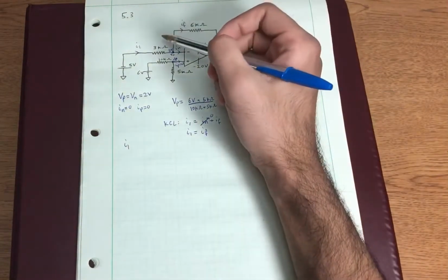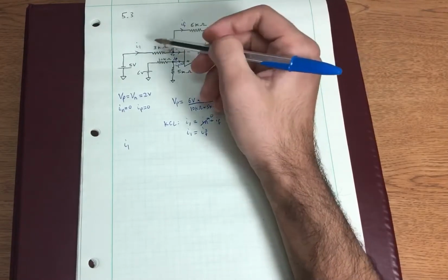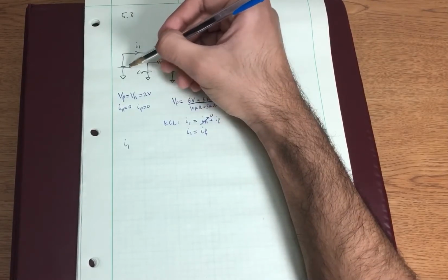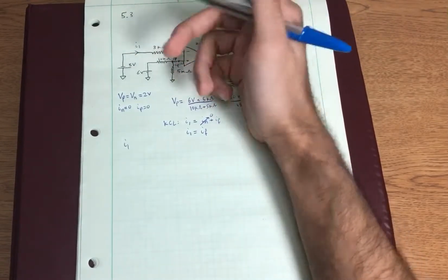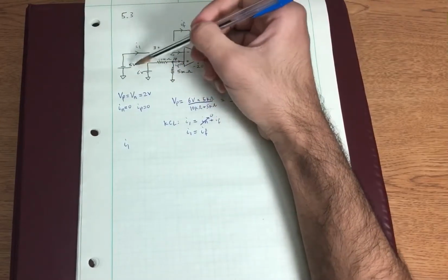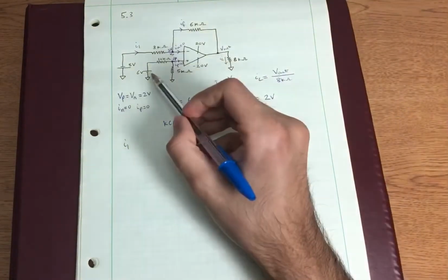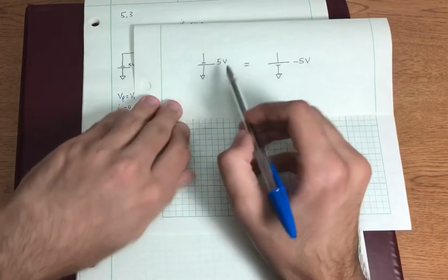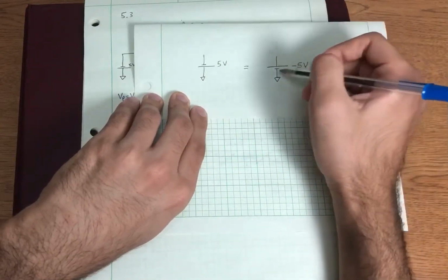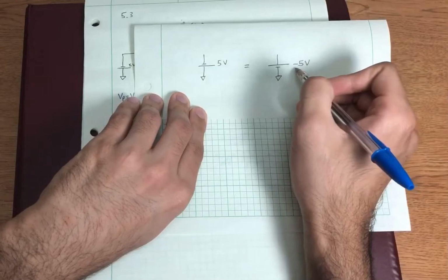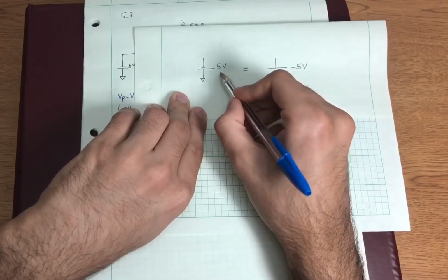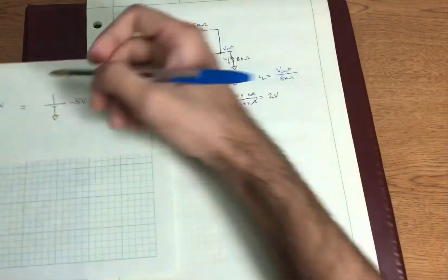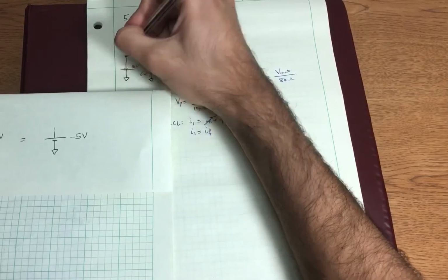So now we know the voltage across this resistor for the current going in this direction. We know that we have a 5 volt source here, but notice that this 5 volt source does not have the regular polarity we're used to seeing, like this one. This one is flipped. We can think of it like a traditional source, except with a negative sign. We can say that this voltage is equal to a negative 5 volt source. So if we think of it like that, then we're just going to have negative 5 volts right here at this end.